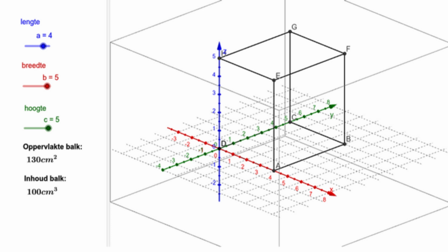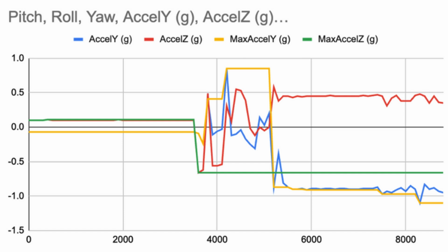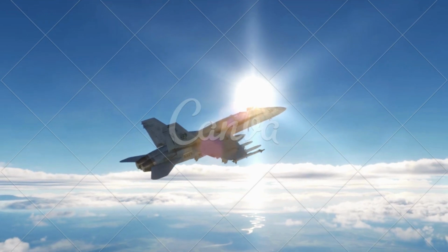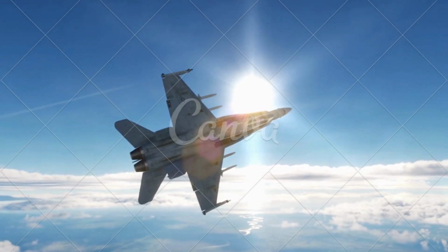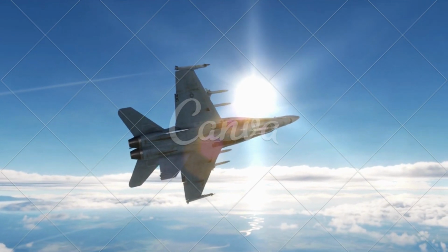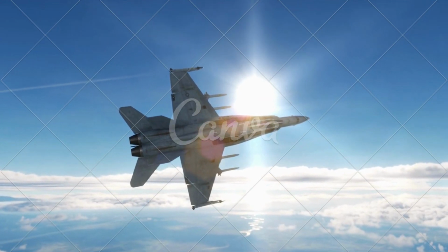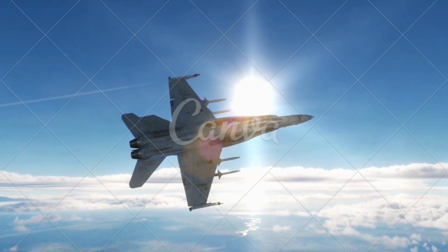Our instrument head records a linear acceleration along the x, y, and z axes plus angular acceleration. This gives a full 6-degree freedom snapshot of every impact. To interpret those numbers, we express each peak as a multiple of g, which is 9.81 meters per second squared, which instantly tells us how many g forces the head feels. The g is also the same as gravitational acceleration.